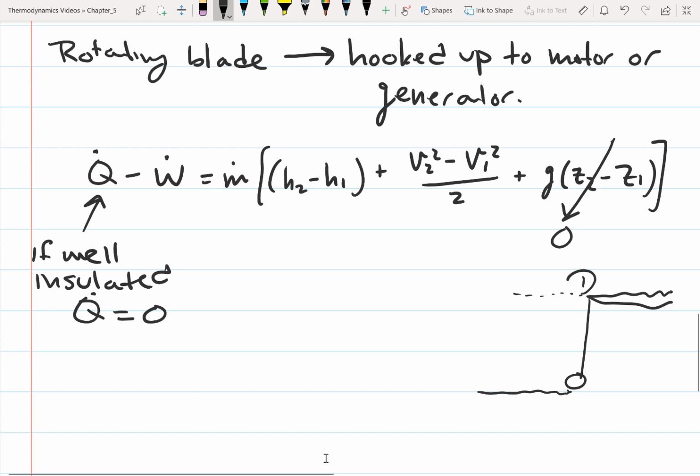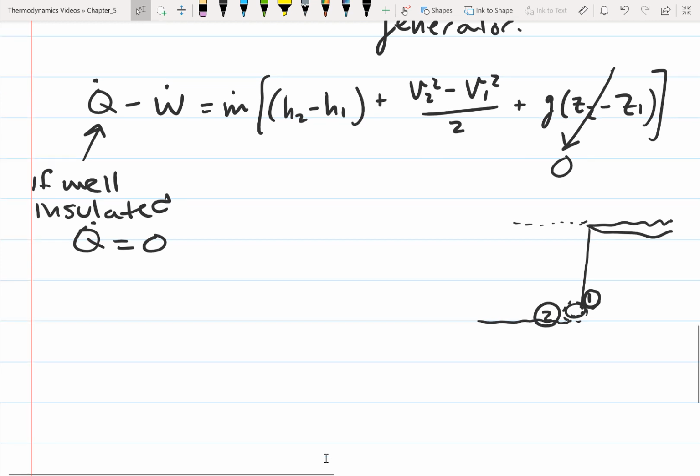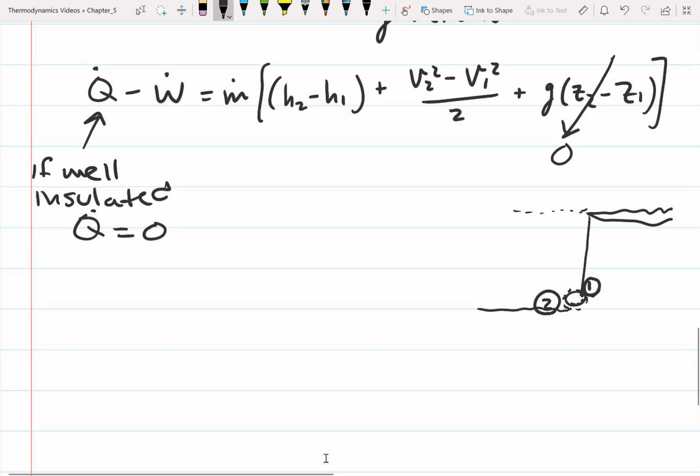So we have been looking at the potential energy, but you have to look at how you define your system. Like if we're defining our system like this, then yeah, we need to consider the potential energy. Consider the turbine as our system. So this is our system. So we're looking from here to maybe here. So basically there's not a large height difference across the turbine. So then we say that the potential energy is approximately 0, but then we need to consider the enthalpy term for the flow work. And we also need to consider the change in kinetic energy. So we will have a velocity change.